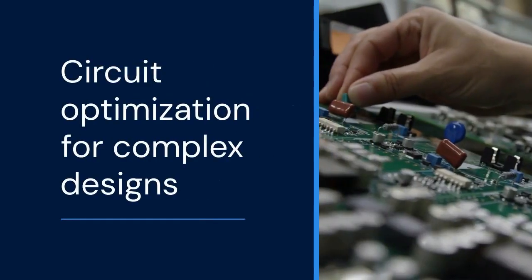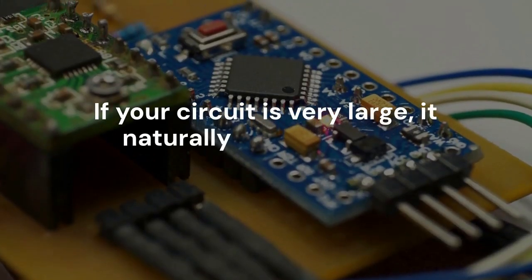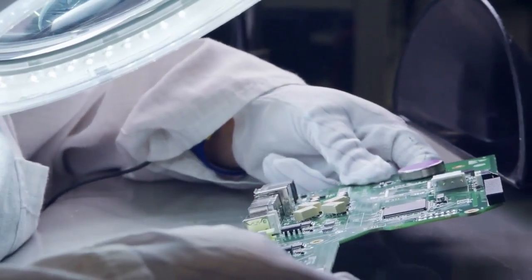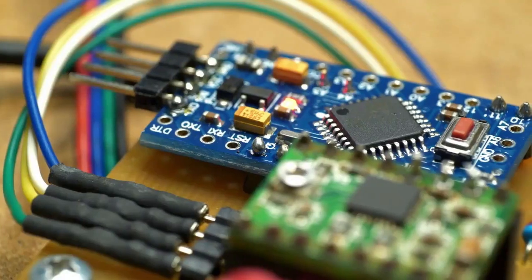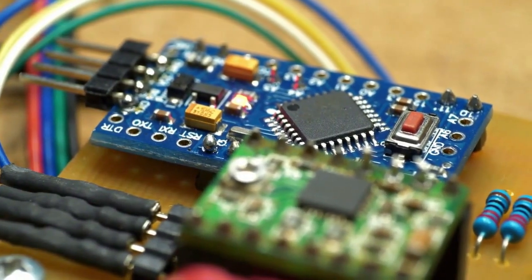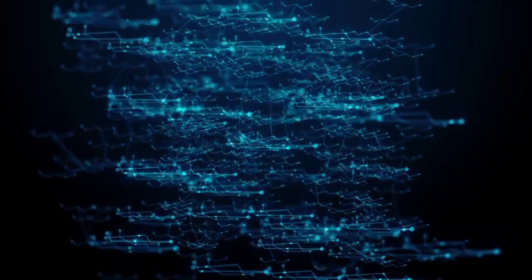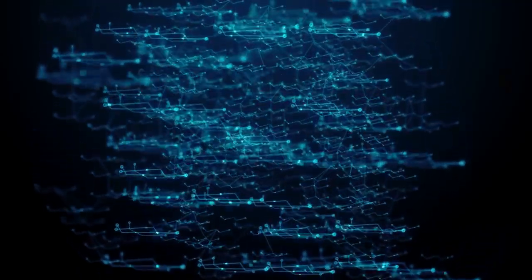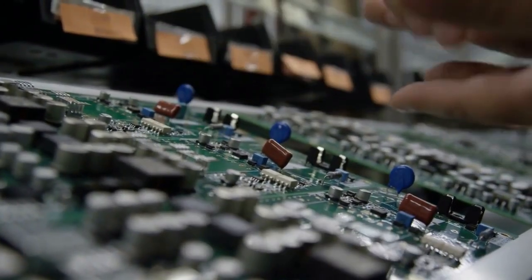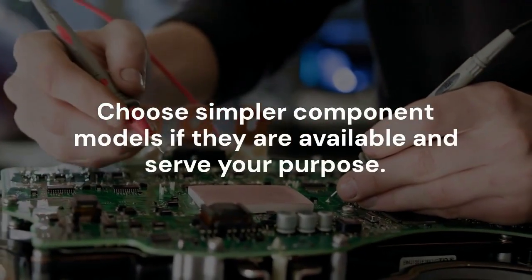Now, let's talk about circuit optimization for complex designs. If your circuit is very large, it naturally requires more processing power. Can you break your design into smaller, manageable parts? Simulate these subsections first. Then, you can combine them later. Try to reduce the component count where possible. Use fewer components if an alternative exists. For instance, use a single 7-segment display driver instead of many individual logic gates. Choose simpler component models if they are available and serve your purpose.